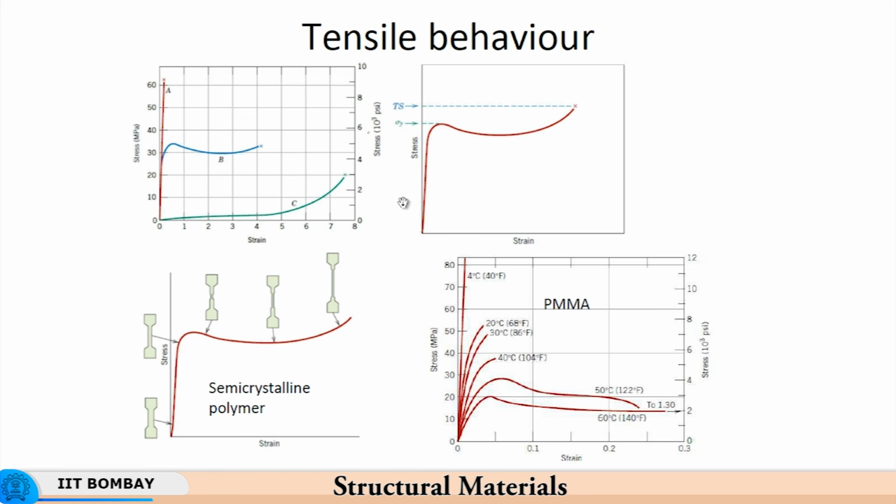The local increase in the deformation velocity will therefore result in a strengthening of this viscous area, and therefore you will have a greater elongation at a relatively lower load. So this deformation is in the presence of a localization of strain. If you have viscous effects, they tend to equalize the strain everywhere.